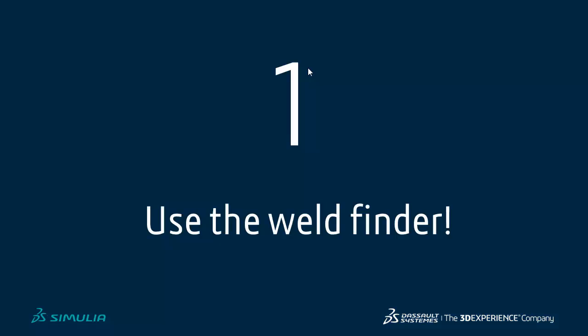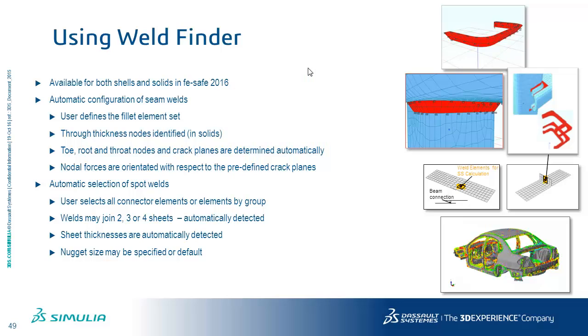And the tip number 1, top tip, and that's because there have been a lot of complaints about the usage of Verity method. It's been quite consuming when it comes to manual definition of welds, and that's why we have developed the Weld Finder. Now we have developed it, we really want you to use it. That's the idea behind it.